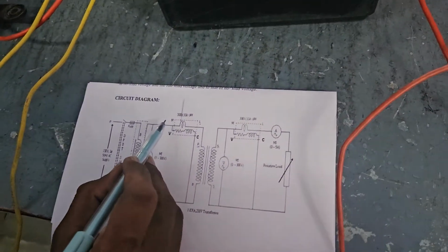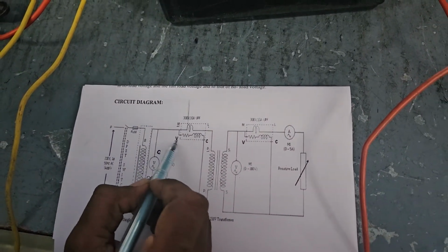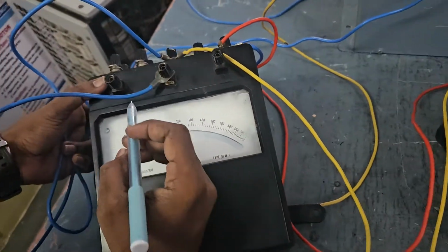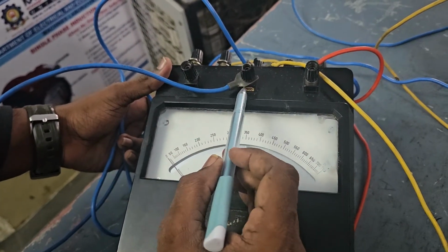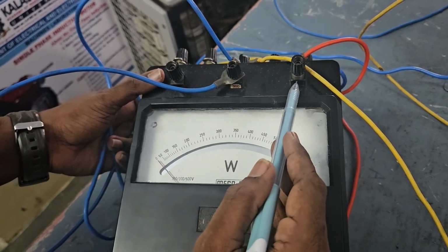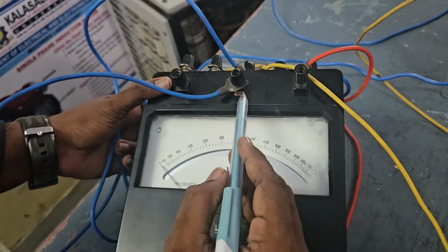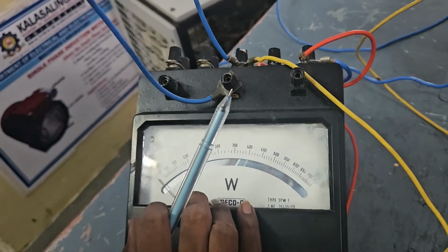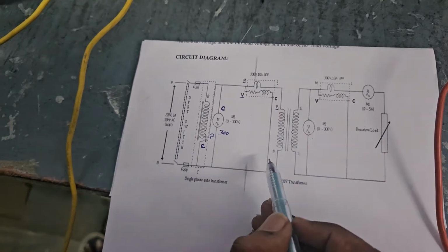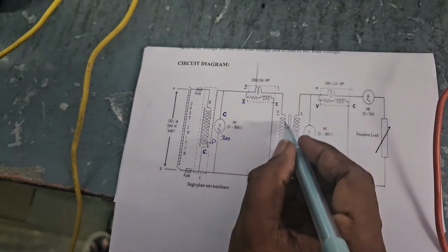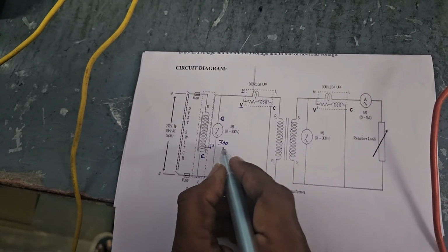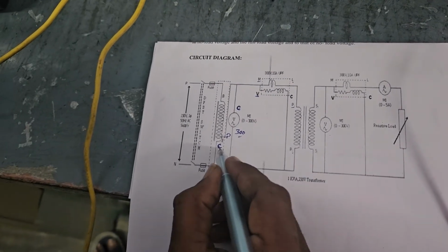And then now I need to connect the wattmeter M and V internally. So let's take from M, and if I see V, there are three ranges, 150, 300 and 75. Depending upon my input level, I need to choose. For our single phase transformer, we need around 230 to 240 volts. So I am choosing the 300 volt range. So I have connected M to the 300 volt range, right? And then the wattmeter common must be connected to the primary winding P2 terminal, and also to either the voltmeter 300 volt terminal or the auto transformer common terminal.